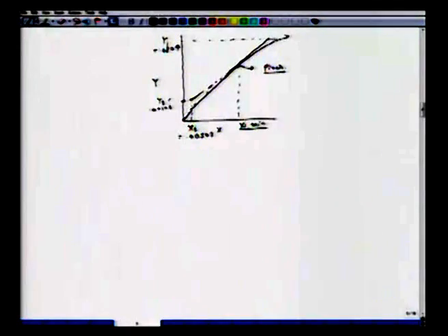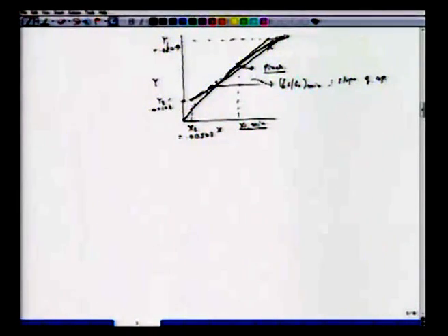So the idea is that if you try to connect directly from here to, let's say, this point here, connecting like this will give you wrong results. So one has to be careful with the shape of the equilibrium curve which we have drawn, to find out this pinch here. Alright. So once we draw this tangent pinch here, we have the slope. We can determine LS by GS min, the slope of the operating curve for this minimum amount of solvent conditions. GS is fixed here. Alright.